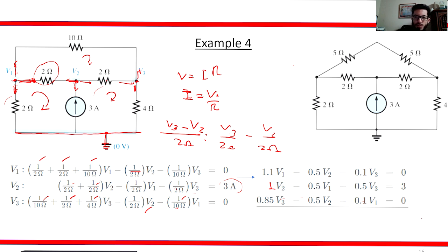So now we have three equations, three unknowns, and this circuit is originally this circuit. Okay, so even though it looks pretty complicated at first, we can set it up like this and it looks a little easier, where right here we have V1, we have V3, and we have V2, and we have V0. So 4 nodes, 3 equations.